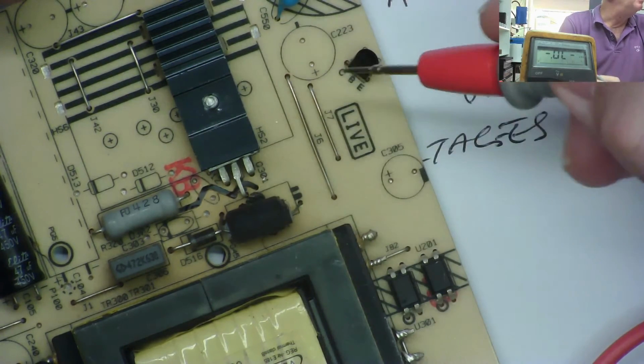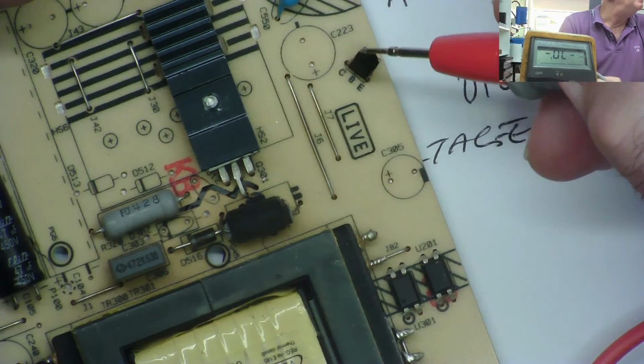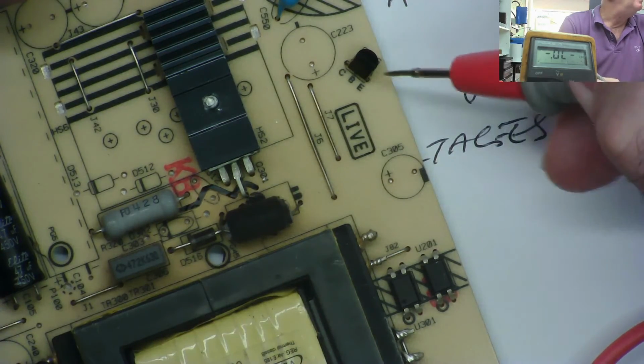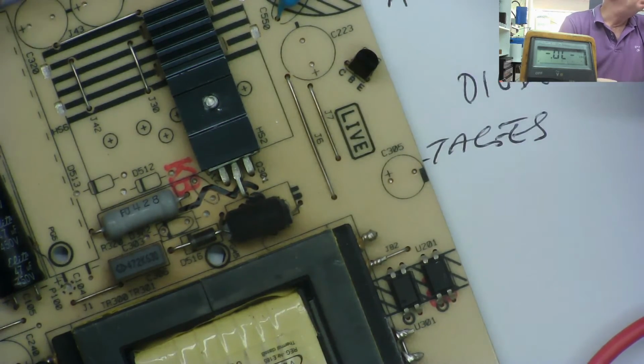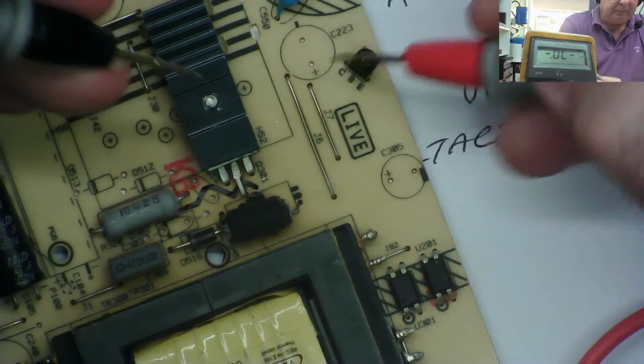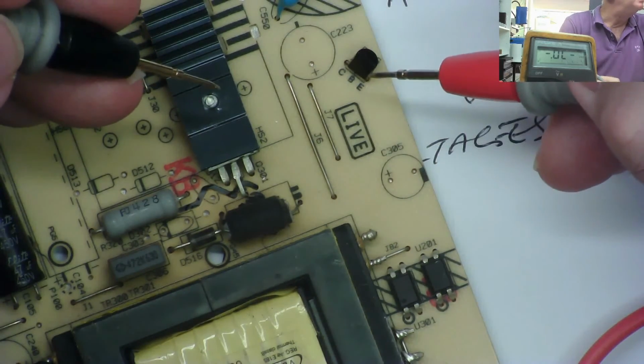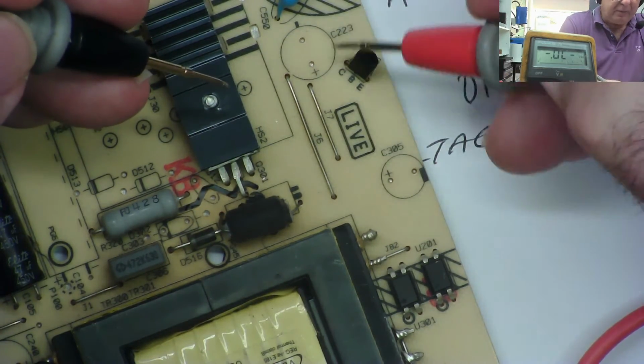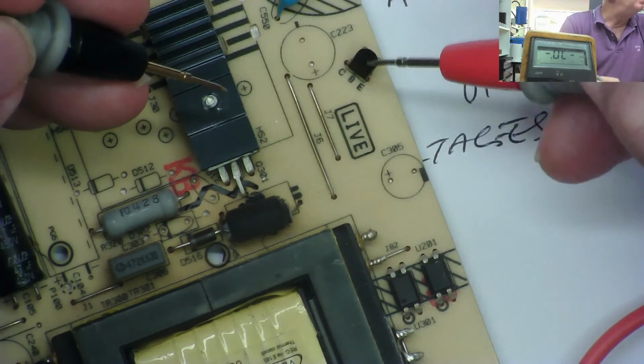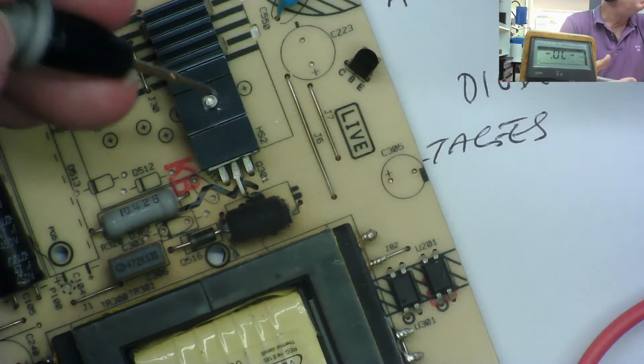This could be connected to another transistor driving it, so the collector drives the base of the other one. And if both emitters are on ground, you would see a diode junction. So it looks like a good transistor. Unless we have some reason to suspect it, we'd probably say it was good. But otherwise, we have to take it out.